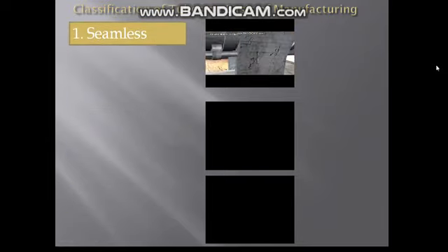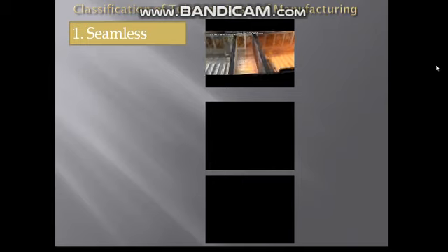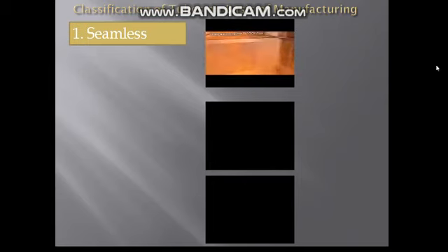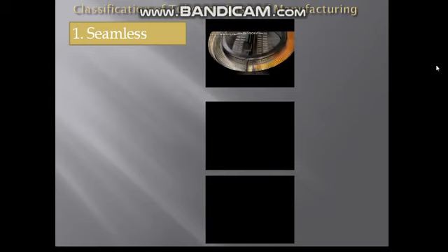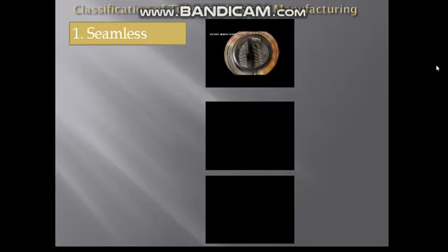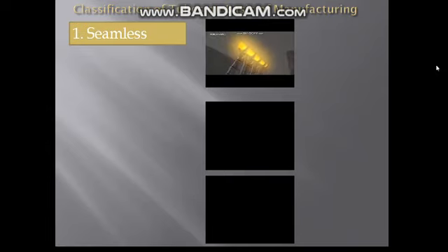In extrusion process, a metal bar, also known as billet, is heated up to 1200 degrees centigrade in a rotary furnace. After achieving this temperature, that billet is passed through piercing mill. In piercing mill, that billet is pulled over a mandrel of desired cross-section against number of rolling dies. After completion of this stage, seamless tube is obtained.